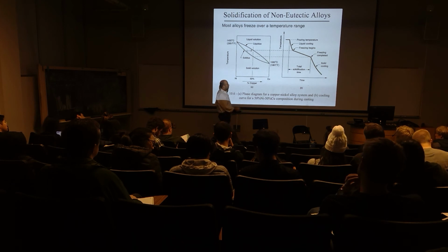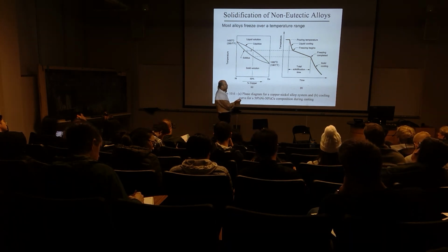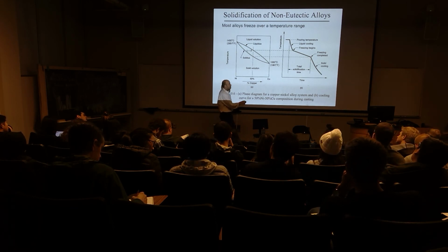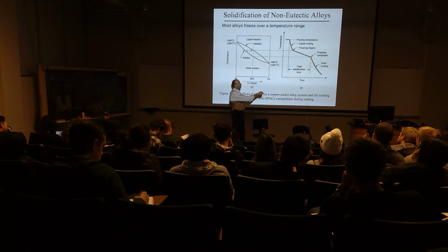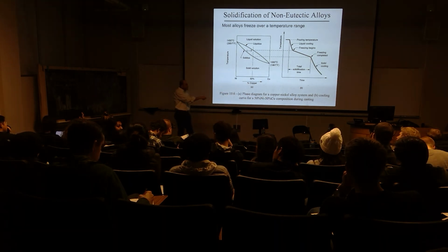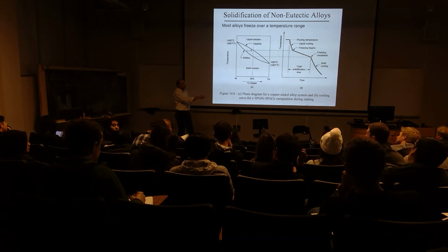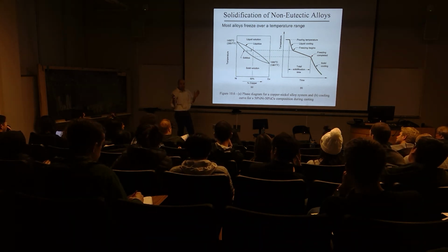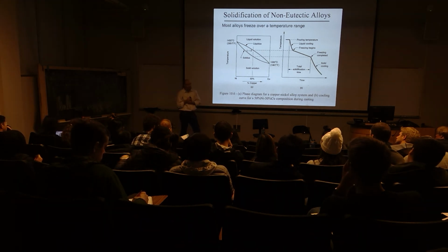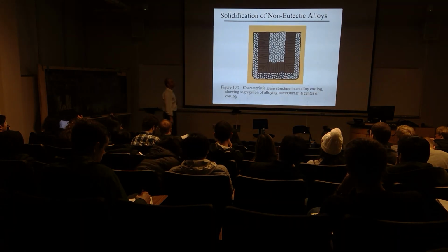Okay? So the total solidification time, again, is this total time from pour to the point where the metal is completely solidified. This is important because, again, the part's going to be shaken out of the mold at that particular time. You can't shake it out earlier than that. You won't wait for the metal to come to here, you'll go here. This part looks like it's the same range for pure metals and alloys, but it's not typically, because in this case, this metal is going through many different things.